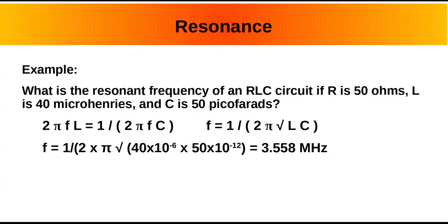So it goes back and forth from electromagnetic energy to electrostatic energy, because you've got an H field in one and an E field in the other, and you're just moving the energy back and forth between them, and it's equal. And that rate of change is the frequency. And that current that's going back and forth is lossless power, because there's no power dissipated unless there's series resistance in it. Does that make sense?